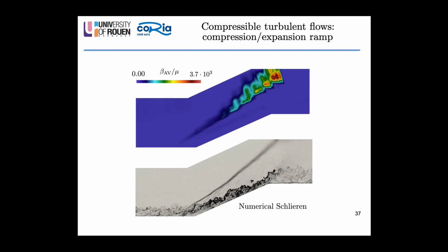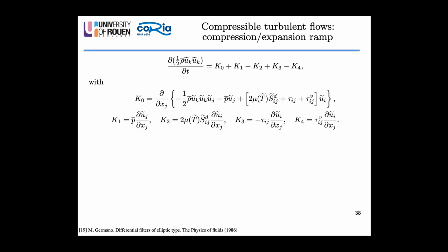On a secondary note, we want once again to reiterate the activation of the artificial viscosity at the correct regions. It's mostly active close to the main shock, whereas it takes quite small values close to the compression ramp. And this is very important because, from a physical point of view, it's well known that this region is characterized by strongly compressible small-scale oscillations, and excessive dilation dissipation in this region would give a completely different kind of physics. But what we are actually interested in this setup is to study essentially kinetic energy transfers under more